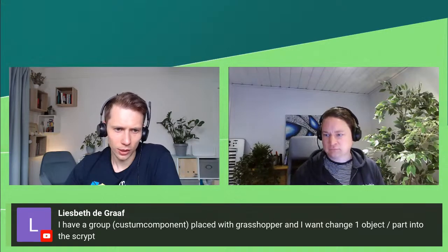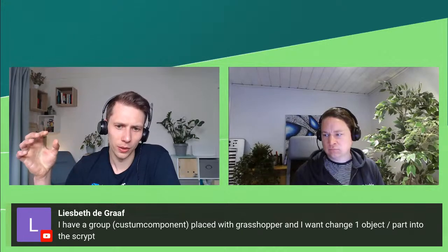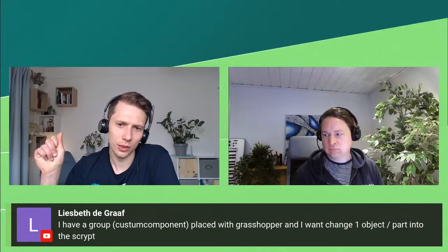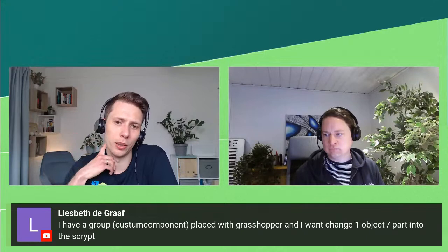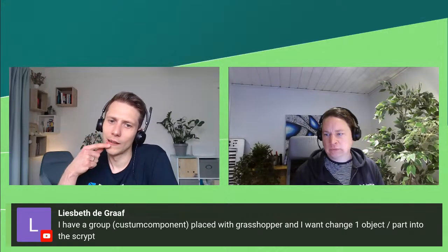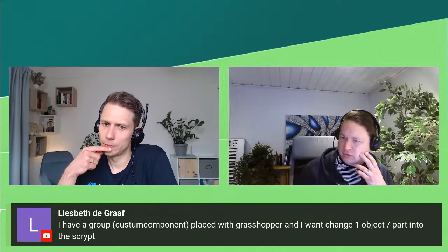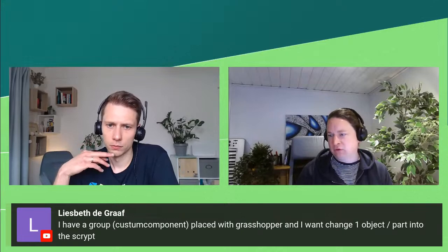Elizabeth has the following question: I have a group custom component placed with Grasshopper and want to change one object part in the script. So let's say that we have some custom components and I want to change one object part in the script. If we can receive some information from the component, and for example let's say we have just one beam or one column from this custom component. I'm not sure if that's what we're looking for here, but you can deconstruct a component using the Deconstruct component in Grasshopper, and from there you can get the objects that it has generated, and then you can use, for example, the Modify Beam component to change it.